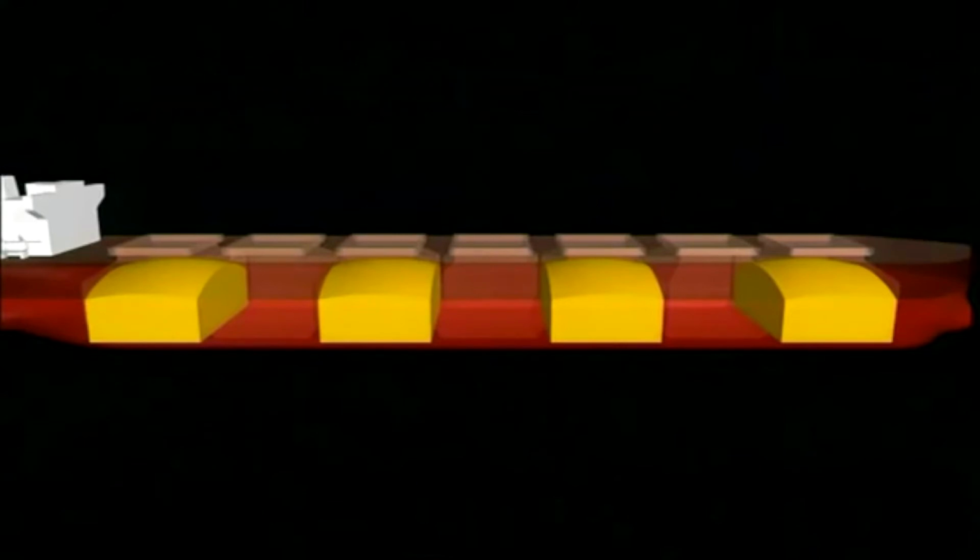When high-density cargoes are stowed in this manner, the weight of the cargo in each hold is approximately double that carried in a homogeneous load distribution. As a result, this requires a vessel to be strengthened and classified for this loading configuration. And under SOLAS, vessels over 150 meters and more than 10 years old are forbidden to use alternate loading unless certain conditions are met.